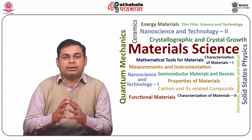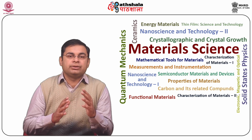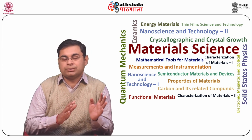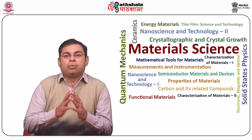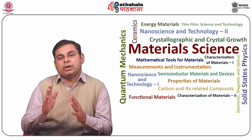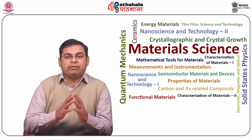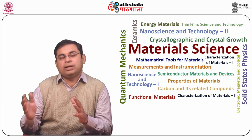As a matter of fact, the density of carriers in a semiconductor is much lower than in metals. Therefore, VH is higher in semiconductors than in metals for given current, magnetic field, and film thickness values.